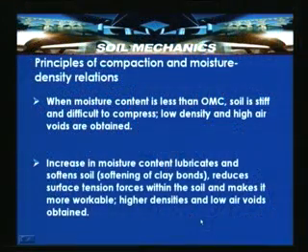So, here water plays as a lubricating agency and softens the clay bonds. So, in the process what will happen is that it reduces the surface tension forces within the soil and makes it more workable, and higher densities and low air voids can be obtained. So, this is a very important concept we should remember about the principles of moisture density and compaction. Increase in moisture content lubricates and softens soil, that is, softening of clay bonds occurs and reduces the surface tension forces within the soil and makes it more workable. Because of this higher densities and low air voids are obtained.